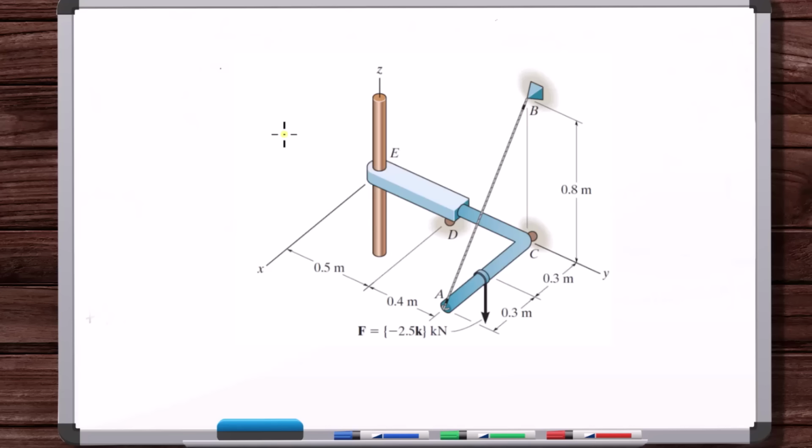You bring a component or a system of connected components into empty space. Typically, you're just dealing with the body forces. Typically, you're just dealing with gravity. Get the center of mass in 3D. Finding the center of mass in 2D or 3D is the same thing. The process is the same; there's just an extra dimension. Put the weight acting at the center of mass down, or toward the center of the earth. It depends on how your coordinate system is oriented.